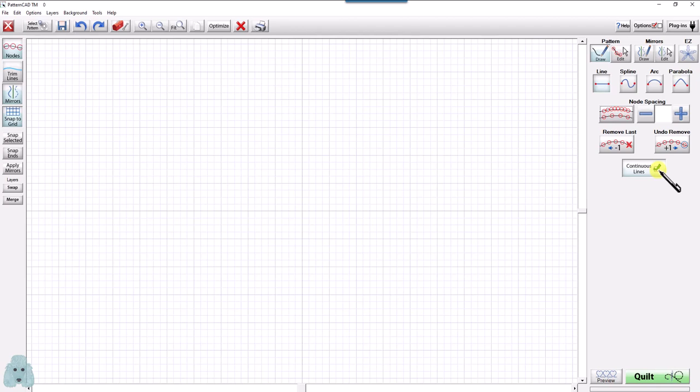All right, so now with my draw selected, I'm going to hold my left mouse button down and I'm going to choose one of the grid lines, hold the left mouse button down and drag to the right. And notice even if I get off of that straight line, it will come back and snap to grid. I'm going to release the left mouse button and now I've created a straight line with 2 points. Green means go, red means stop. So I have a beginning and ending point all on the same plane.